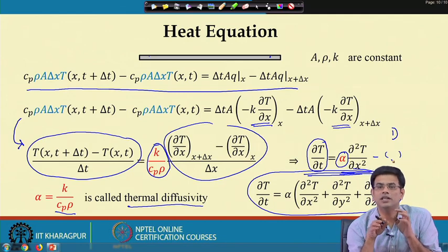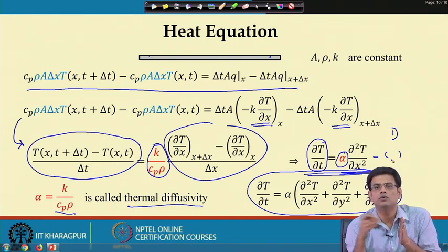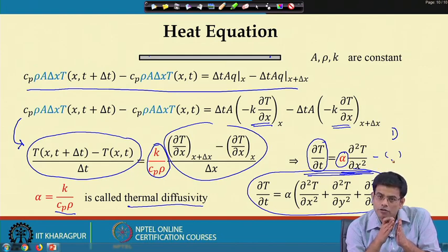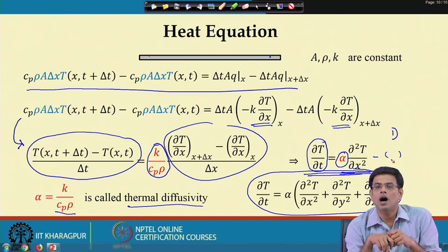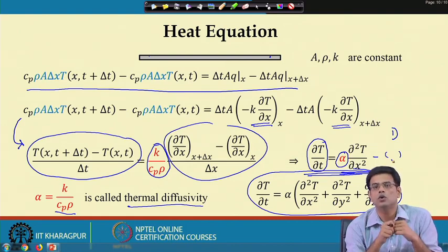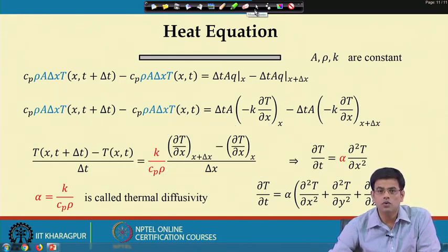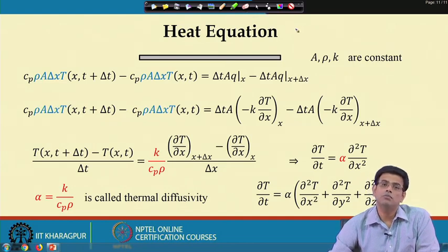So, the basic objective of describing this is that the heat equation governs the heat flow in the material, and the purpose of the heat equation is to know the temperature profile from this side to this side of the material. Because in elasticity, when we solve the effect of thermal stress on elastic material, we need to know the delta T. How do you find delta T? Actually, you need to find it from the heat equation. So, this was the objective. I stop here, and in the next class we will start the general uncoupled form of elasticity, thermoelasticity. Thank you.